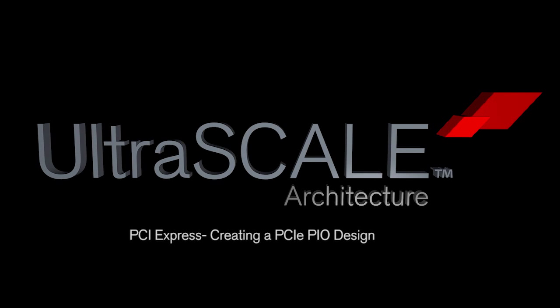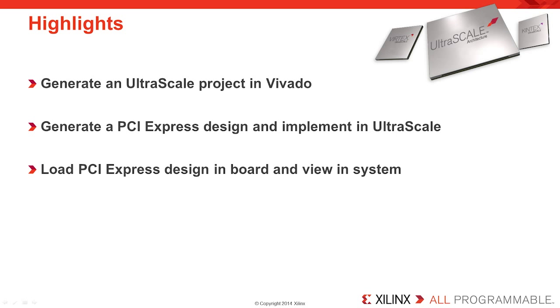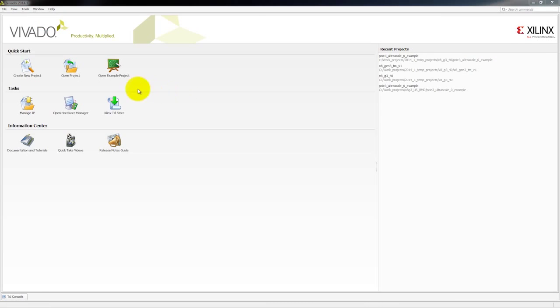Welcome to the UltraScale PCI Express example design quick take video. Today we're going to walk through creating a PCI Express design in the new UltraScale architecture in the Vivado software. Once we generate the core, we'll implement it in Vivado, take it all the way to a board, and then load it into a system and look at what we can see in that system using some standard Linux commands.